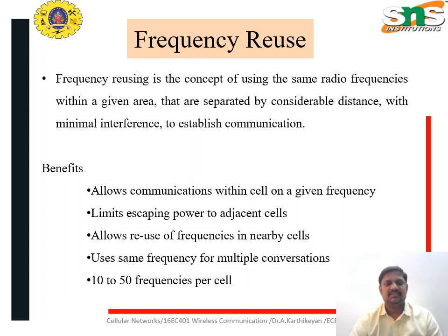The main benefits of frequency reuse are that it allows communication within the cell on given frequencies with limited escaping power to adjacent cells, and allows reuse of frequencies in nearby cells, using the same frequency for multiple conversations. Around 10 to 15 frequencies per cell we can use in the frequency reuse concept.